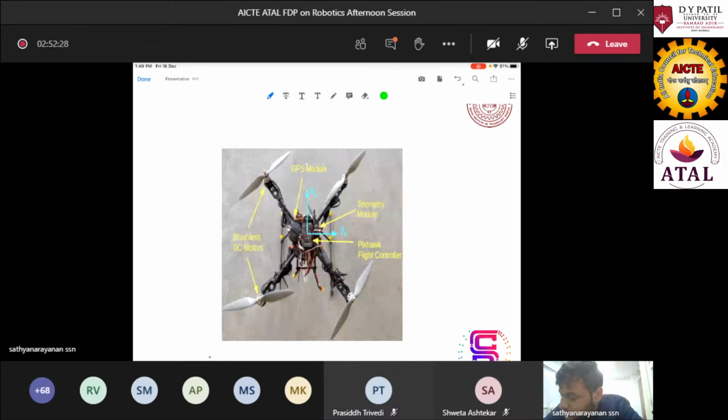here the rotor is powered by a unit which consists of a motor, which is a BLDC motor, which I have right here. And this is why BLDC is used: it is small in size, has higher efficiency compared to a brushed DC motor, and has a longer lifetime also.